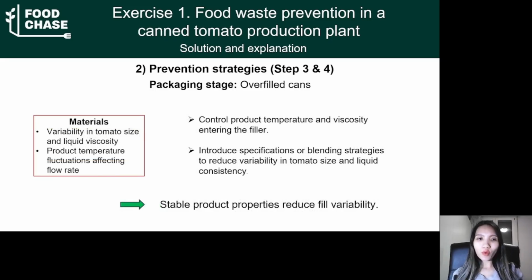For the cause in the material category, we can control product temperature and viscosity entering the filler. So it's actually an inline control. And then we can introduce a specification or blending strategy to reduce the variability in tomato size and liquid consistency. This solution can help reduce the fill variability.